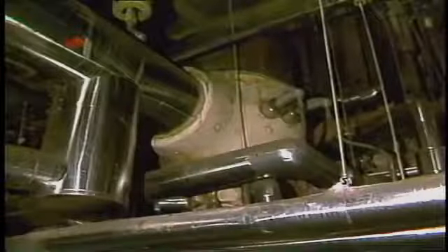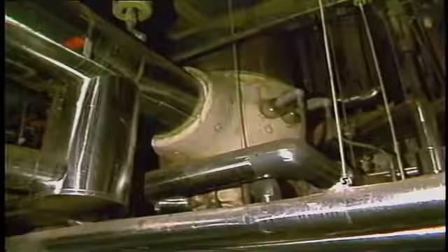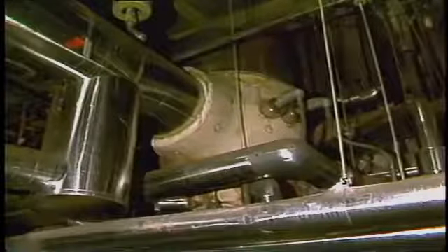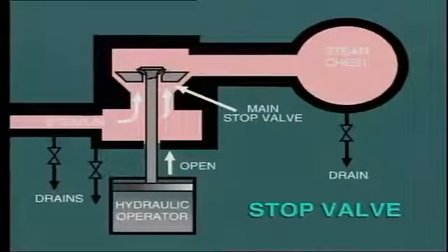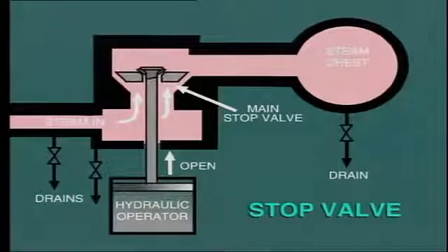An extremely important test maneuver is the exercising of the turbine stop valves. The test circuit allows the stop valve to partially close and then open again. This test is performed daily in many plants, and the objective is to make sure that the stop valve does actually move and not remain frozen in the open position, as has actually occurred on some occasions. All of the protection devices in the world would be of no use whatsoever if the stop valve failed to close when commanded.